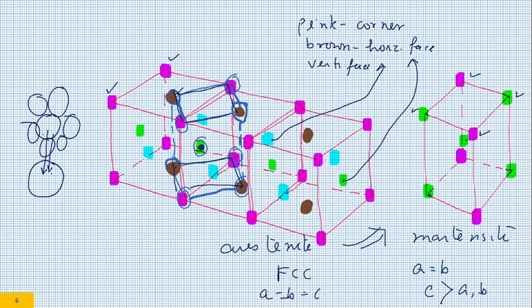So if it is trying to expand, the existing surrounding unit cells would not allow it to expand to such an extent. So you want to expand, you are not being allowed to expand. So here, if there is a volume expansion upon transformation, it would not be allowed to expand to its full extent.